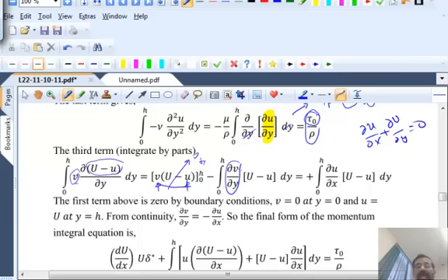So I take this dv dy and replace it by minus du dx. That's why the sign minus becomes plus, and this becomes du dx instead of dv dy. What have I achieved so far? I've gotten rid of v from my equation. So I'm getting everything in terms of u, the lowercase u, and the deficit, the difference between capital U and small u.